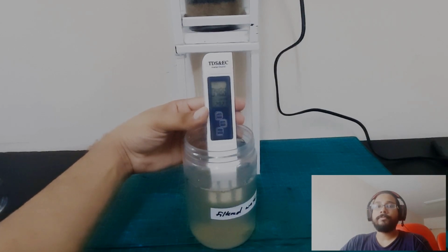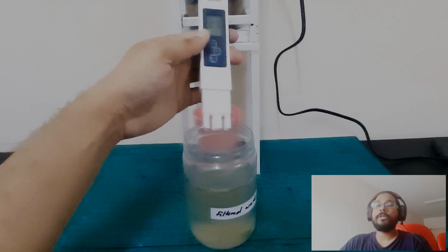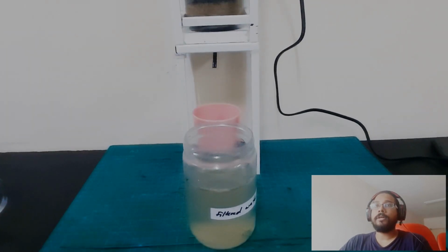So if the flow from the sedimentation level is reduced even further and the particles are given even more time to settle, it will help to improve the quality of the water. Also, the sedimentation of the device can be redesigned in such a way that only the top portion of the water is transferred from the sedimentation level to the filtration level, so that the sediments at the bottom will remain without being mixed with the filtered water. Due to this design flaw in the sedimentation level of the device, some of the sediment particles formed were passed along from the sedimentation level, which contributed to the increased turbidity of the treated water.